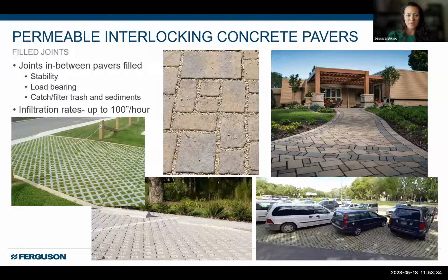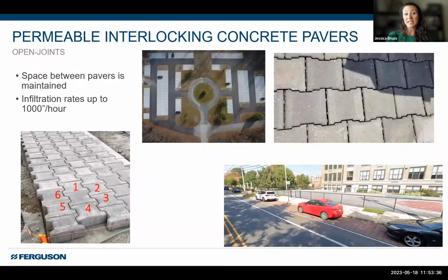And then, of course, just depends on how that surface is maintained. Now, our open joint paver systems are going to be different, where we don't have that sand infill or gravel infill. We actually see this open joint that's about 1/4 of an inch. You can also see that we have essentially these gaps, that's where the water runs in between. They're large.